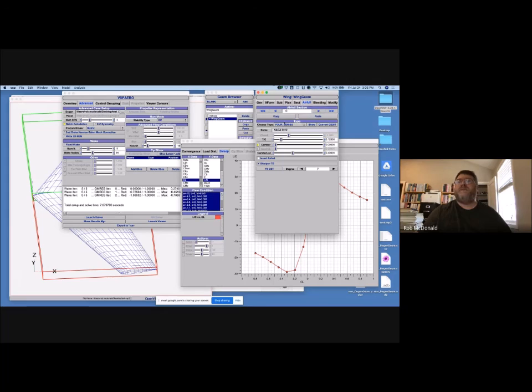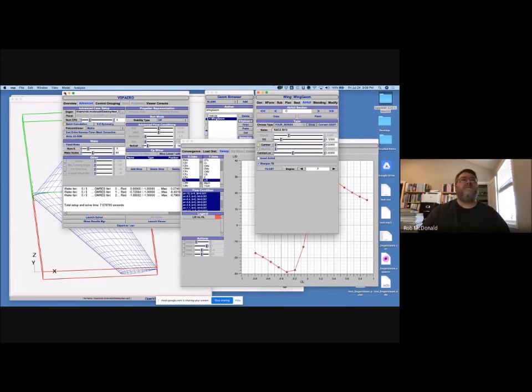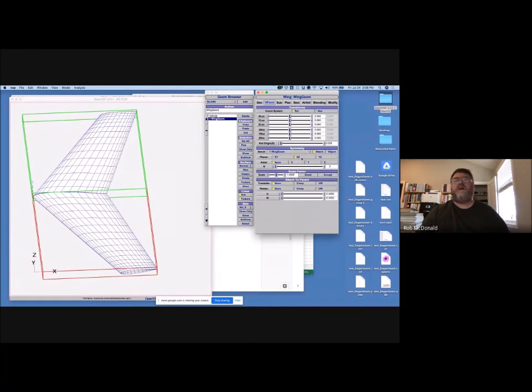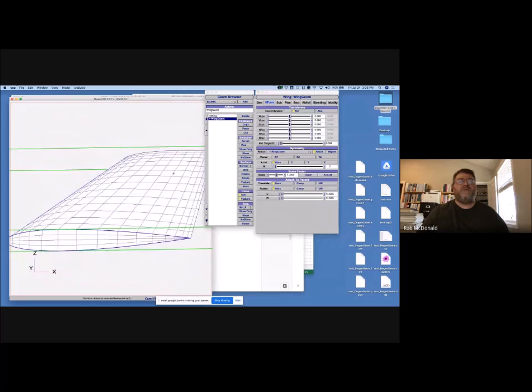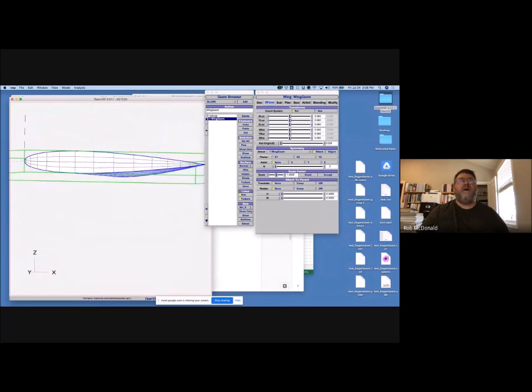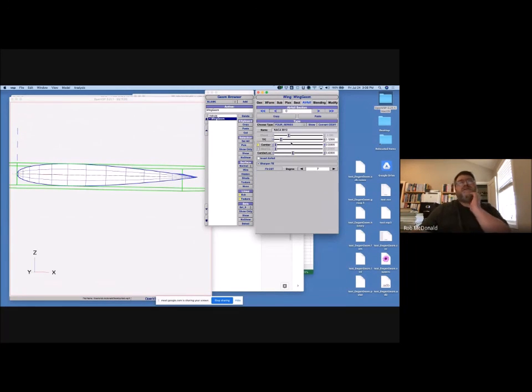So here we have one of these airfoils, and let me show this airfoil. Let's turn that off. Now we're looking at the root airfoil, trying to look as close at that as we can. And we're here at the root. That's a NACA 0012, so it's 12% thick, and the maximum thickness is at 30%. So that's an airfoil. There's this button down here that says Fit CST.